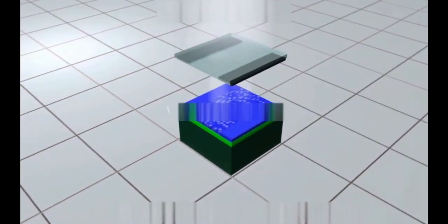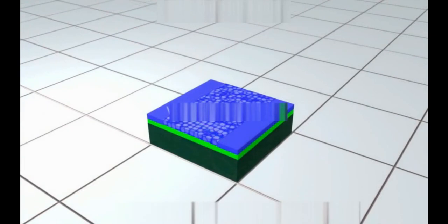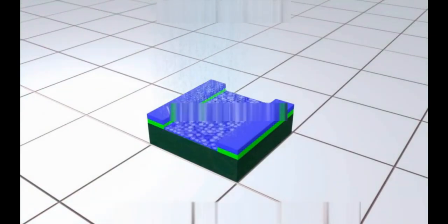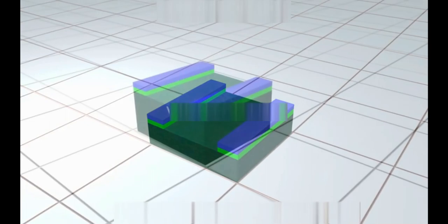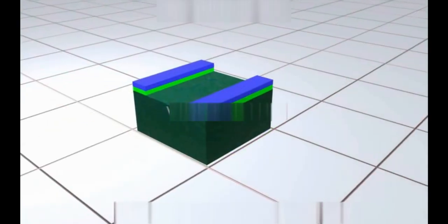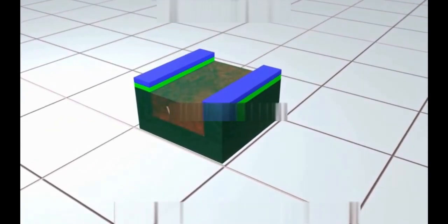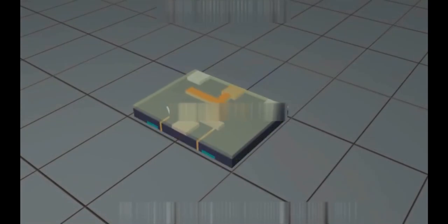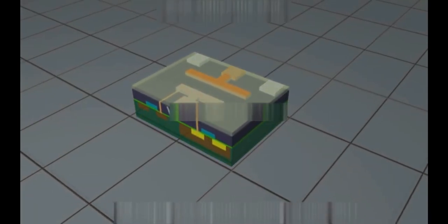The regions exposed to the photoresist are then removed using acids in a process called etching. The unexposed regions protect the lower layers from reacting to material deposition, thereby forming specific patterns. The process of photoresist application, lighting, etching, and material deposition is repeated several times until several millions of transistors are created and connected, forming several hundreds of chips on one wafer.